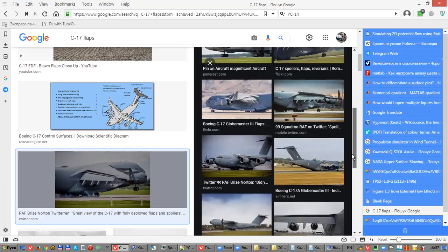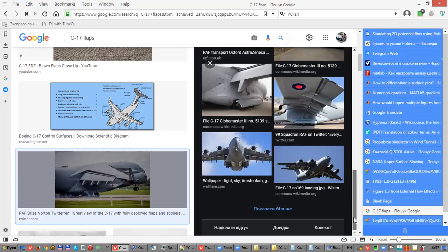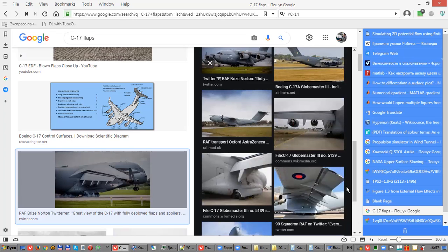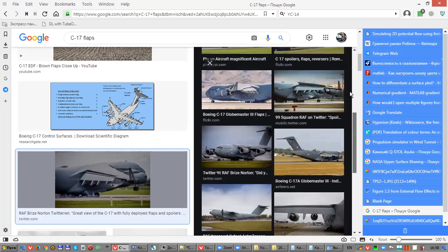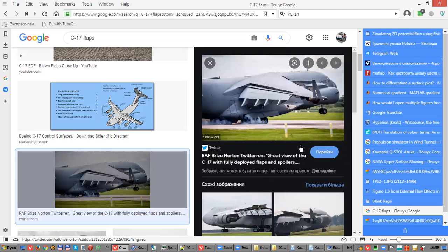But in this configuration, the flaps are immersed in the jet stream only in lift condition. When the flaps are in cruise configuration, the jet stream doesn't affect the aircraft characteristics. So this configuration has better cruise and fuel efficiency, but maybe not so good lift.